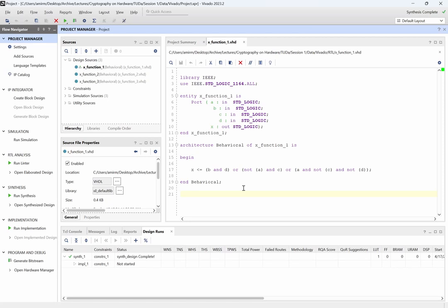If you have a super large circuit that doesn't fit easily inside the FPGA, then it takes a very long time. In general, there is a rule of thumb that you should have 80% utilization for the FPGA. It means that if your FPGA has 1,000 lookup tables, you should not use all the 1,000 lookup tables, because the mapping and the routing will not be possible, and it takes ages for the tool to try to map, and it gives up after, let's say, a couple of days. But for the examples that we have for this FPGA, they fit easily inside the chip, and the mapping doesn't take that long.